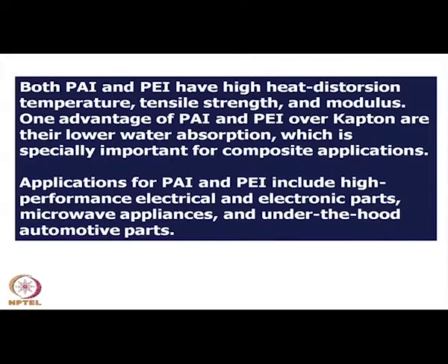Now, both this polyamide imide and polyether imide have a high heat distortion temperature, meaning they are dimensionally rigid at very high temperature, and provide very high tensile strength and high tensile modulus.